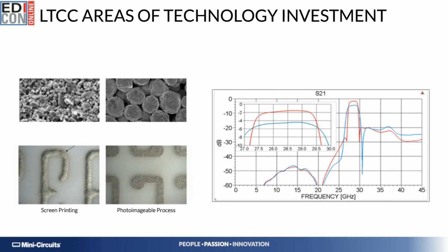allows for much tighter spacings between conductors, along with a much higher silver concentration of the paste. This translates into the possibility of realizing tighter couplings, reducing lot-to-lot, unit-to-unit variations, significantly reducing insertion losses by having much smoother and higher conductivity conductors.